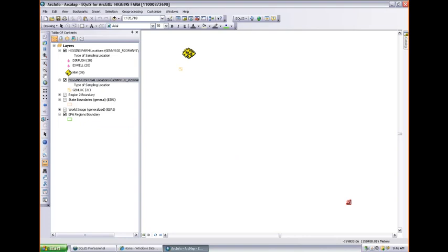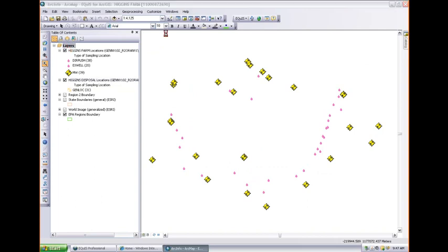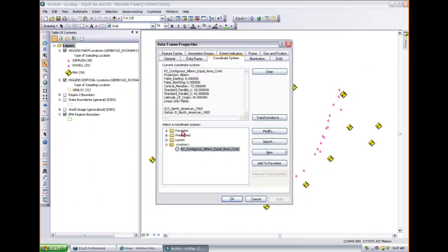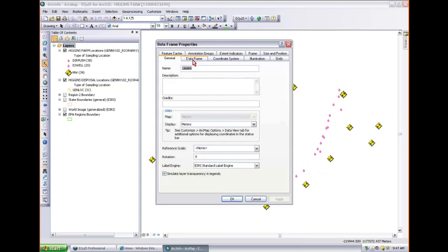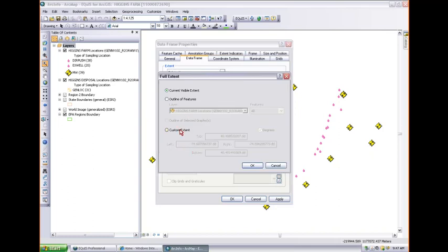Like these samples either had the wrong coordinates or they belong to another facility. That'd be my guess. The facility ID may have gotten entered wrong. So what you can do in that case, because the issue would be when you zoom out, you always get your view very far away, you can override the zoom. So this is really where our facility is here. And if you're working with a facility that has a broad range, you can always just go here and override the extent, so you don't have to zoom out really far all the time.